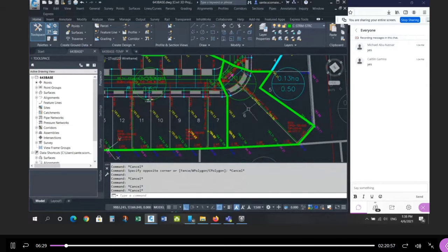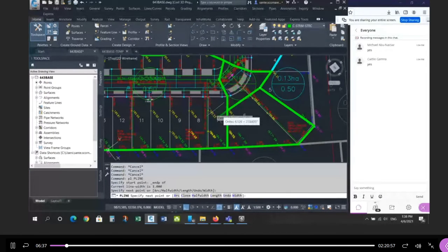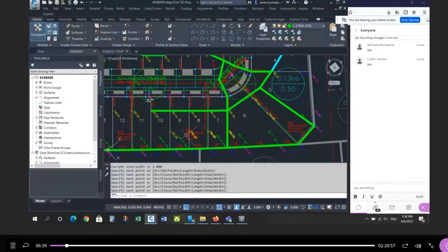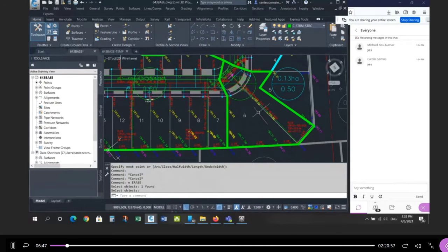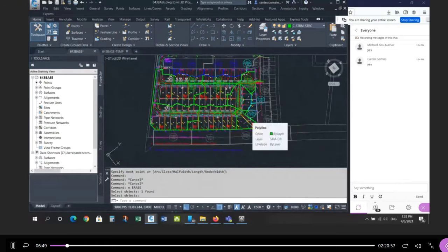Right? So there was one catch basin connected to this short pipe, and I combined it to what was happening on the street. Remember, the drainage divide used to be here. So this area and this little area combined to give me this total area now, because that backyard gets into that street pipe. So that was the rationale.